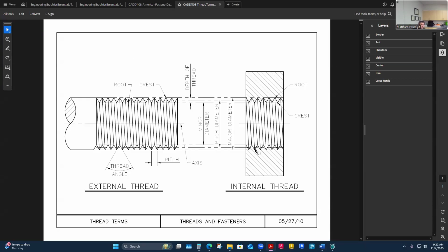No, you don't have to there. What's going to notate that is that UNC or UNF, just the fractional form of that, is going to be my visual indicator that I'm not in a metric fastener. So yeah, that's a good question, but not needed for the units.